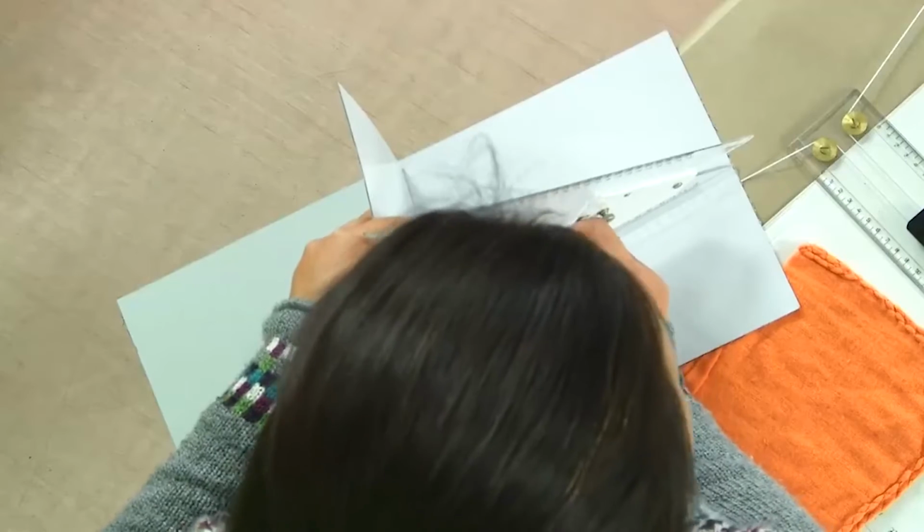So, we have a horizontal plane and we have a vertical plane, and the line which is inclined to both the planes is contained in a plane which is perpendicular. So, this plane, say the set square, is perpendicular to both HP and VP. So, this is the plane. Now, if I have a line which is inclined to both HP as well as VP, whatever that line is, the sum total of the angles that it makes with HP and VP will remain 90 degrees.